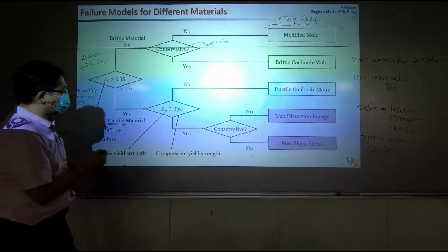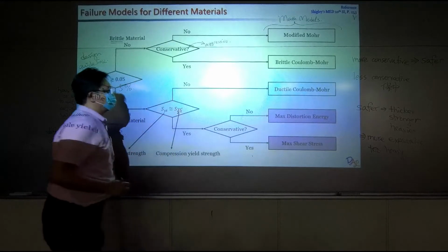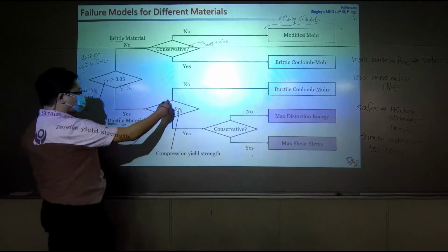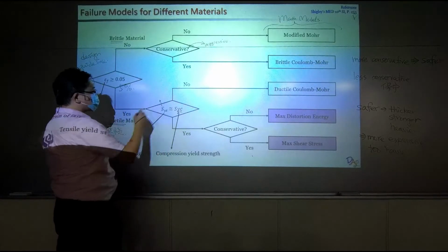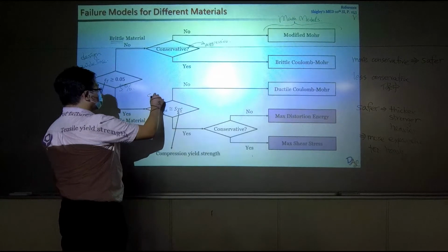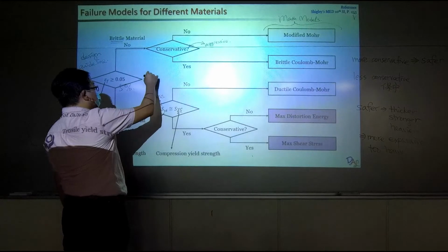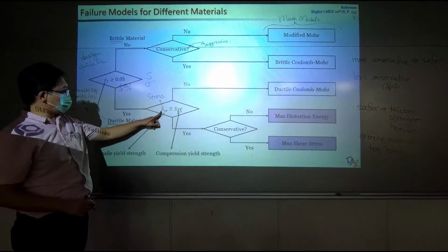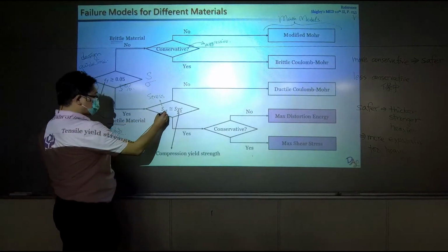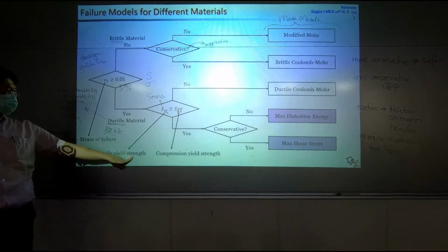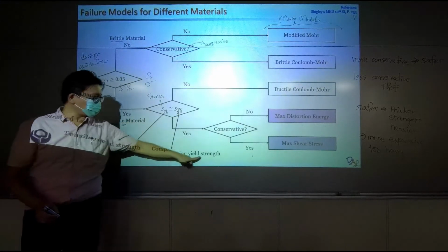Now this should be lower. So what does that mean? What is this check? S is basically also stress. Sometimes we use sigma, sometimes S. So what does SYT mean? Y is yielding, T is tensile. So this is tensile yielding strength, and SYC is compression yielding strength.